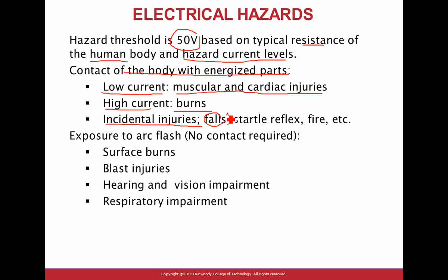Say you have a storm, and there are stories, guys, of electricians working on a panel when there was a storm. We get a lot of storms in Minnesota. What do the storms do? Lightning hits the transmission line. What happens when lightning hits a transmission line? That big pulse of voltage goes right through the line down into your facility. If you're in close proximity and you have a transient, it could go all the way down to that panel.